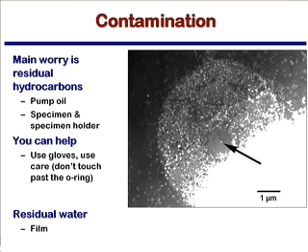I was trying to look at the growth of these little holes in gallium nitride. If you have a screw dislocation in gallium nitride, it may have an empty core. It does this to relieve the strain associated with the large Burgers vector of that dislocation. And so I was doing a bunch of experiments where I was holding it for various amounts of time at high temperature and watching those things grow to characterize the kinetics of that.